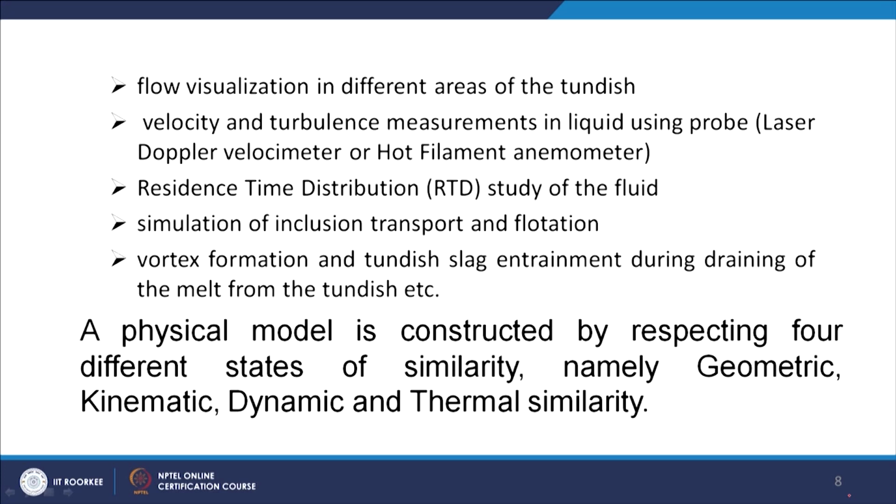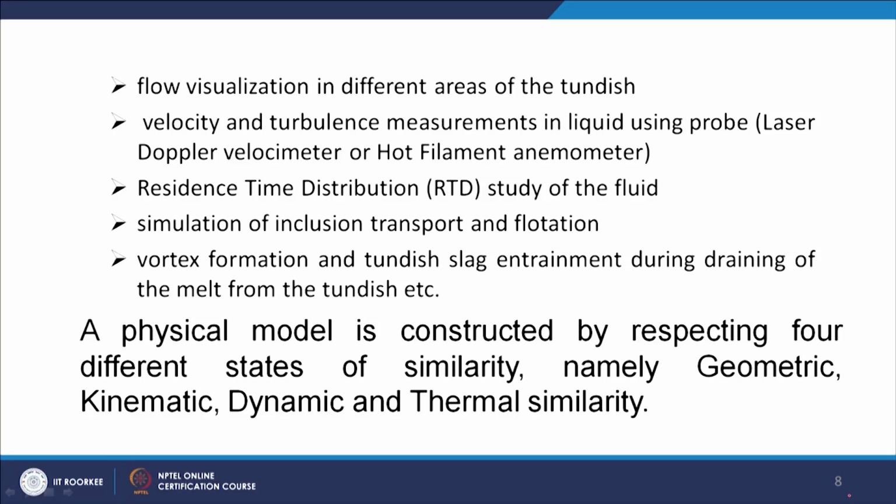You can do the RTD study of the fluid. RTD is the residence time distribution study. We do that by tracer dispersion studies, and by that you can get a feel for the time for which an individual fluid particle stays, or on average what the stay time of the fluid inside the tundish will be. That is your residence time distribution, and you can have that at different points inside the tundish.